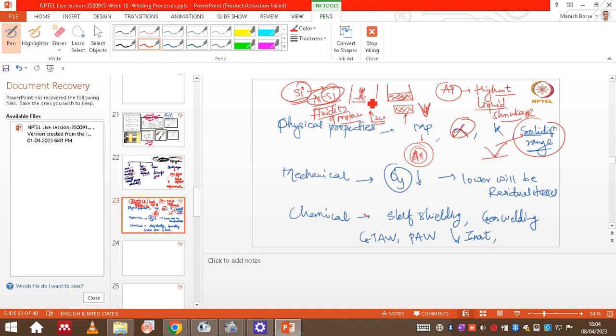So when it solidifies, it will release that extra heat, and because of that, molten liquid will always be there at the interfaces or interdendritic region. So it will fill the shrinkages that are forming, right? So it's kind of good if we add silicon for increasing the fluidity.